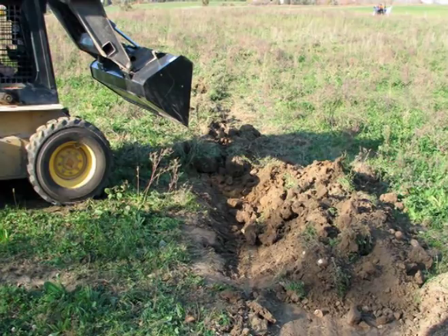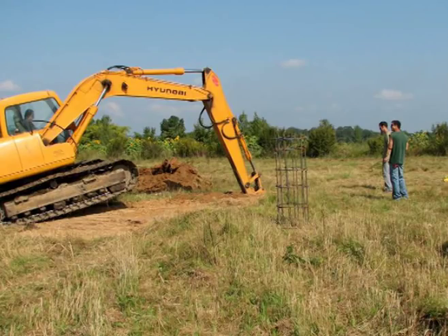My favorite tool is a bulldozer with a 6-way blade. It means it can take the blade, tilt it this way, and drop it down, and it's just like a plow. And another reason why I like it is it can make a smooth slope on the way in here. And one of the more critical pieces of equipment for farmers, if they're cutting hay or combining grains, is the cutting bar on whatever your hay equipment is. You can put a wheel right down on the bottom of this trench, and it'll go across here and not cut dirt. You don't want to cut dirt in the middle. It's bad for your equipment.